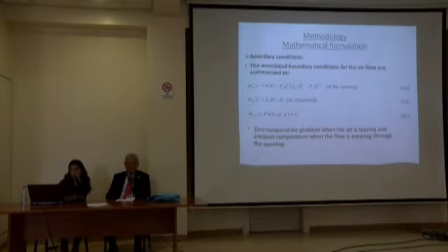Now, the associated boundary conditions for the airflow are summarized as follows. We can use the mass flow rate from Bernoulli at the opening where the flow is driven upward, and then it's zero at the closed end because there's no mass flow rate, the top is closed. Because of the symmetry line, the angular mass flow rate is zero at theta equals 0 and theta equals pi. Then, zero temperature gradient when the air is leaving, and the temperature is ambient at the inlet flow.